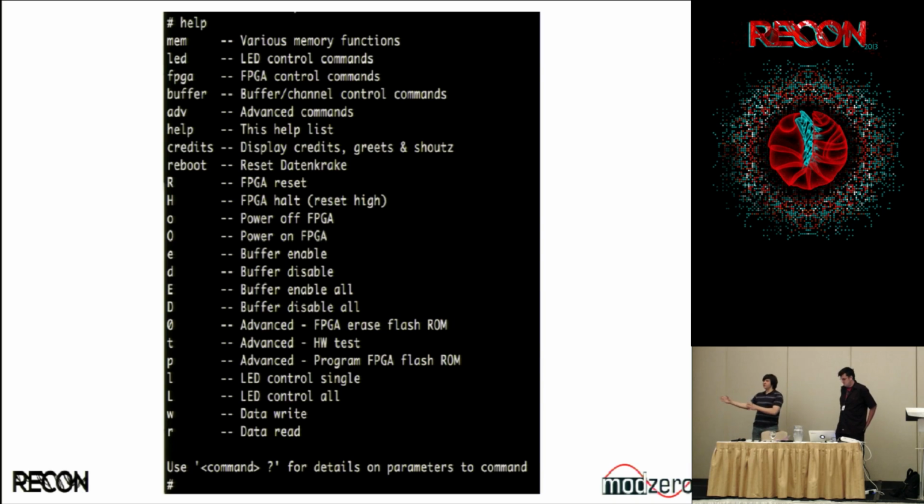So what we did for you is if you implement something on the FPGA, you can write directly with this write command. You say address, data, and 1 second later, all of a sudden, your hardware either starts working or it doesn't, depending on if you did a good job writing the logic or not. But this is a very important feature if you're doing FPGA designs, because it's really annoying to figure out a way how to test if your synthesized design is actually performing as it should.